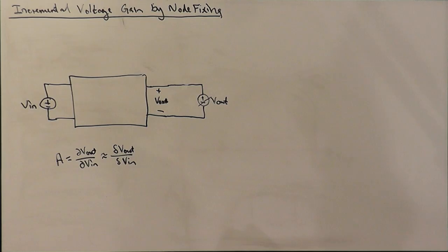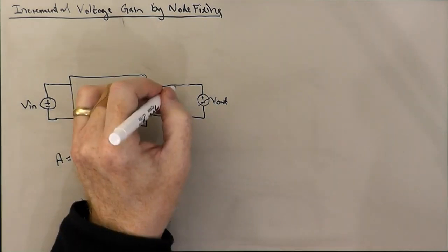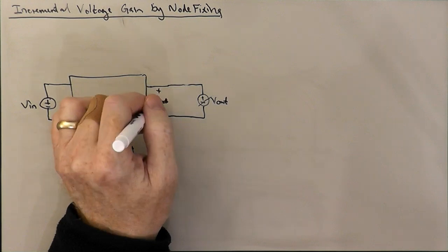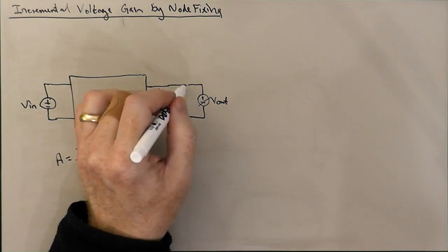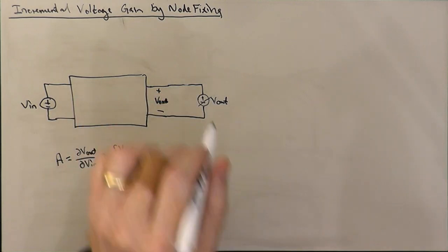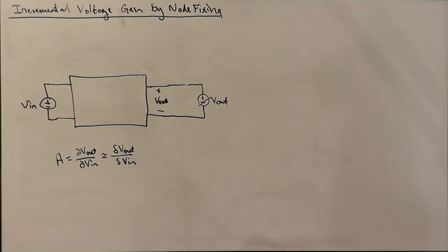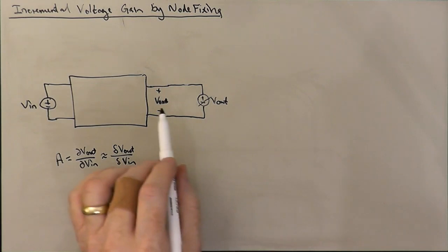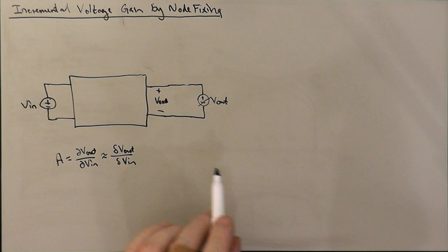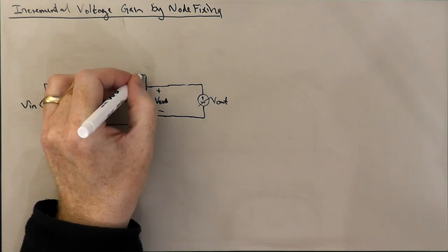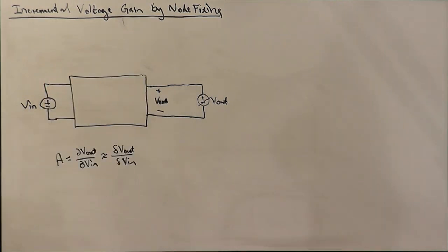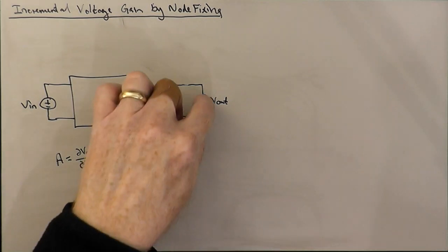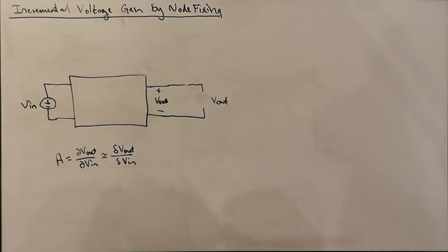Okay? You can imagine, if you like, having a resistor here and saying, well, if this voltage is the same as this voltage, how much current flows through the resistor, and then take the limit as that resistance goes to a short circuit. But basically, if this voltage is exactly the same as this voltage wants to be, there should be no current exchanged between the voltage source and the circuit. Hopefully that's reasonably intuitive. And so, just get rid of this line here.